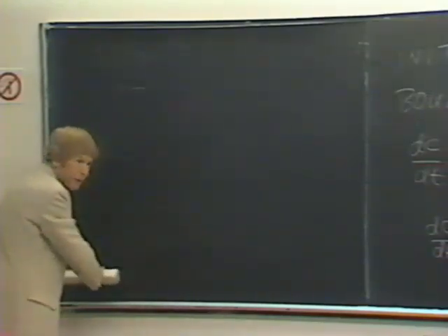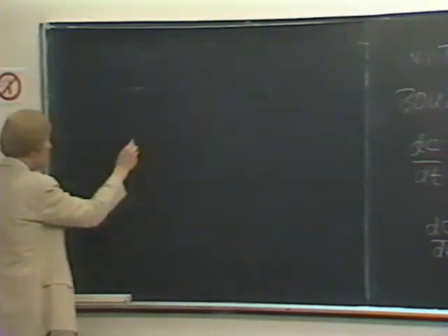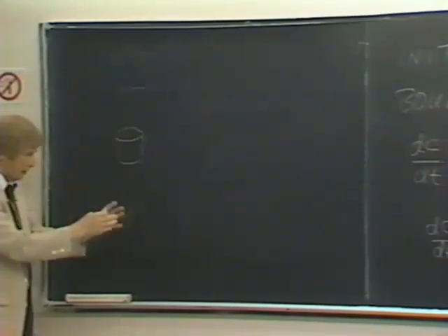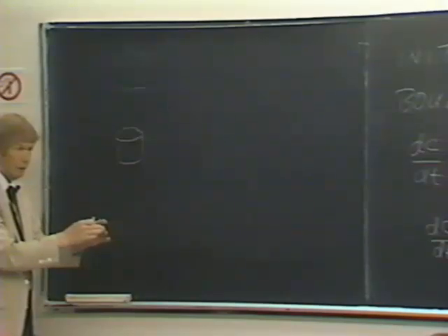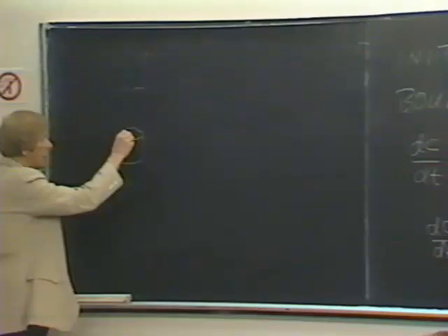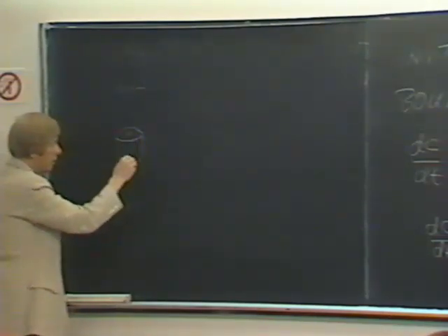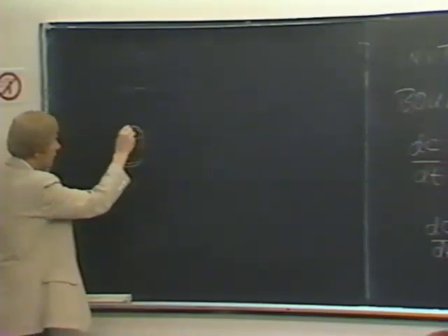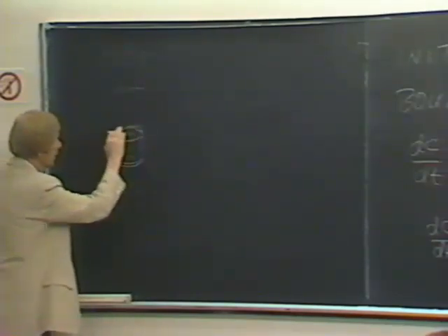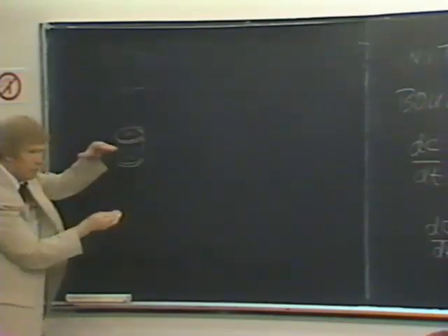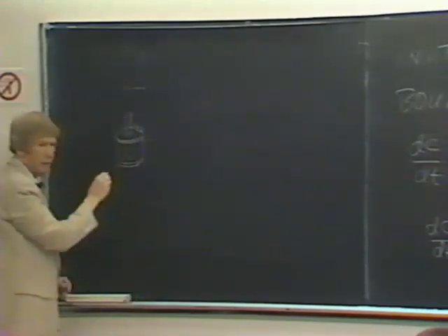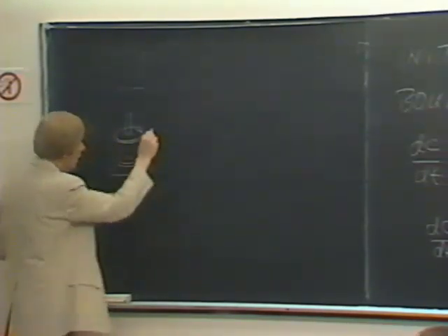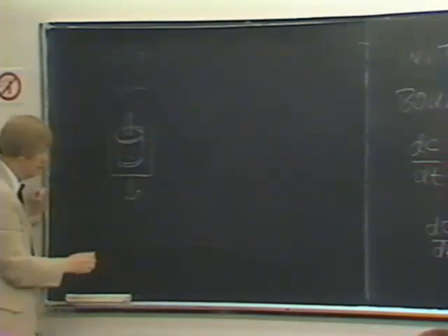Haven't I described the rotating cylinder apparatus? I thought I did. It's you take a cylinder of mud, take a core sample, and keep it in its jacket until you're ready to use it. Make sure it's saturated, and if it was wet to begin with, it's been kept wet. And while it's still in the jacket, you drill a hole in it, and put it on a mandrel that we have down there that simply puts a plate on the bottom. On the top, so that you have mud held on a rod like this. The sample's held on the rod with exposed mud surface on the outside. And you insert that in a rotating cylinder, mounted on a shaft that can be rotated at different speeds, omega, let's say, and fill the annular space with water.